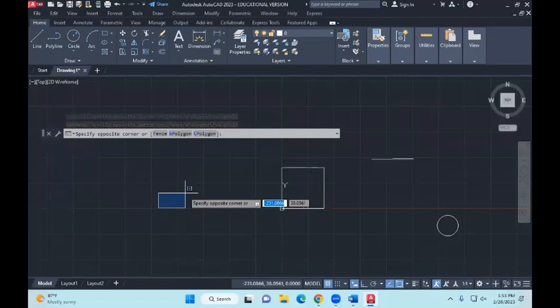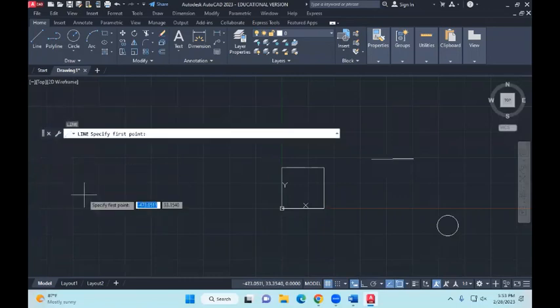information appears, right? Excuse me. So now if you want to draw a line, for example, I'll enter. It says specify the first point. Nothing gets typed in the command area. The command area always remains blank because dynamic input is on.